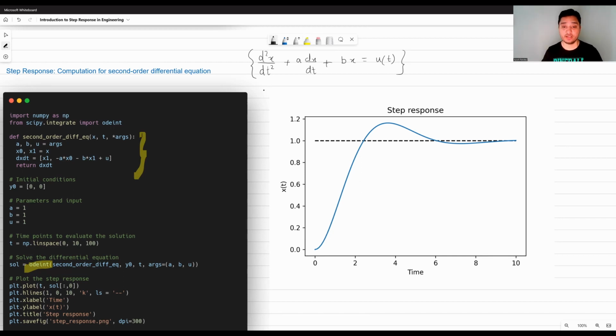So as I mentioned already, we want to use the step response to characterize the performance of a system, or to write the specification of what we desire out of a system using the step response. So how may we do that? Let's go back to the motivational examples that we discussed at the beginning of the lecture, and let's take altitude control, for example. We are at a certain height already, and we want to introduce a step input to that system to take it to the next altitude, let's say from 100 meters to 200 meters. Now, what might be a property that would be desired for the aircraft once we introduce this input?